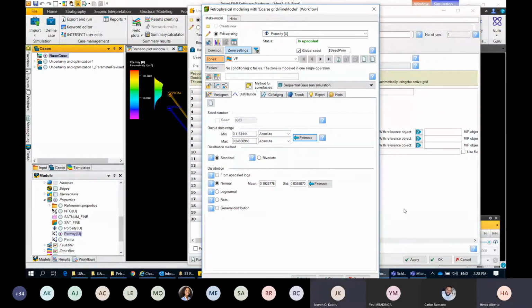Thank you. So if you have minimum and maximum ranges of your porosity and this value is uncertain, even inside your geological workflow, you can define this value as an uncertain value by adding the dollar sign, which represents an uncertainty parameter within the Petrel workflow, and adding the parameter we are defining. This is maximal porosity, okay? And into this process, I click apply and okay.